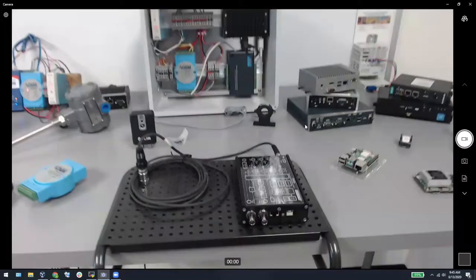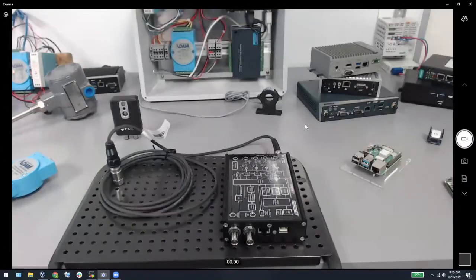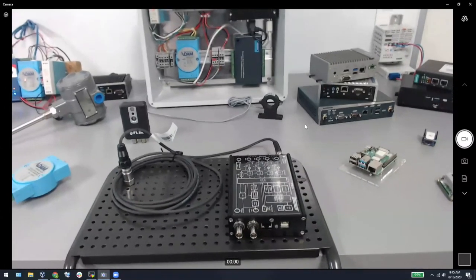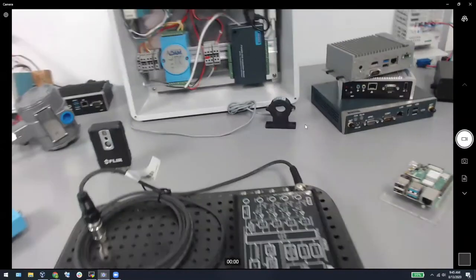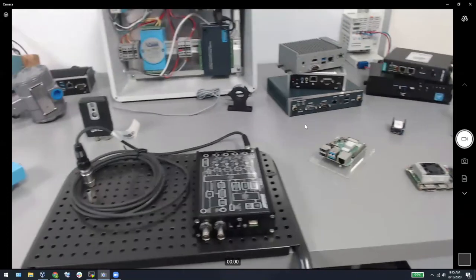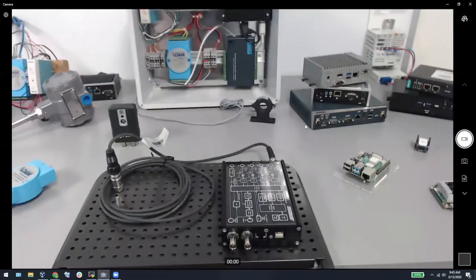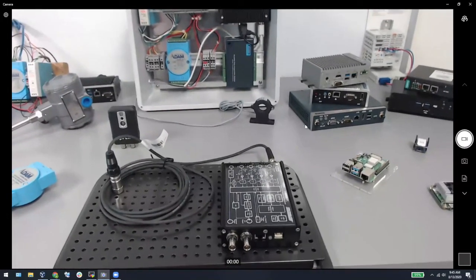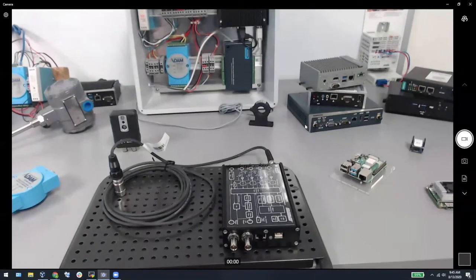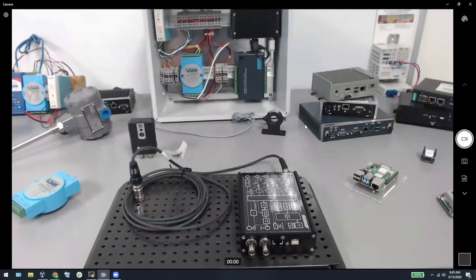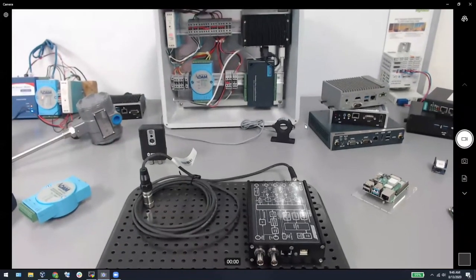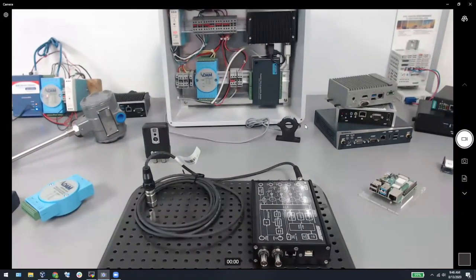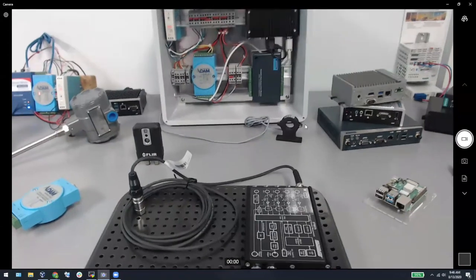And here is an example of a high frequency data acquisition module that we would ingest data from. The accelerometer here would connect up to a data acquisition module. This is a 4-channel data acquisition module with tachometer input as well, so as to guarantee that the sampling rate is held steady across a single master clock, and so that you could do your analysis in a synchronized way.